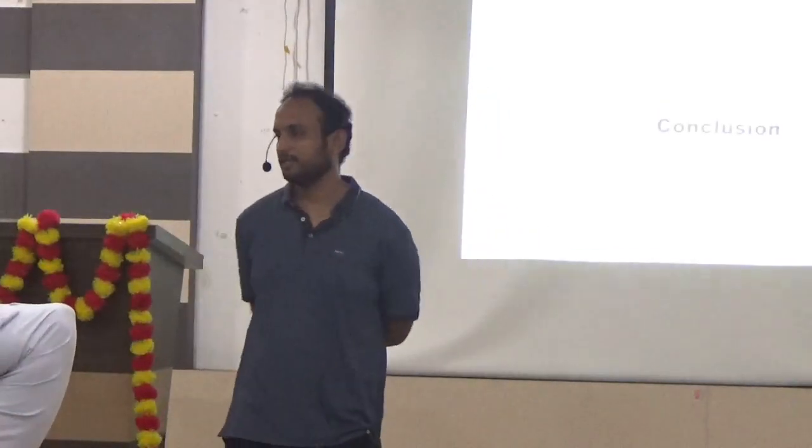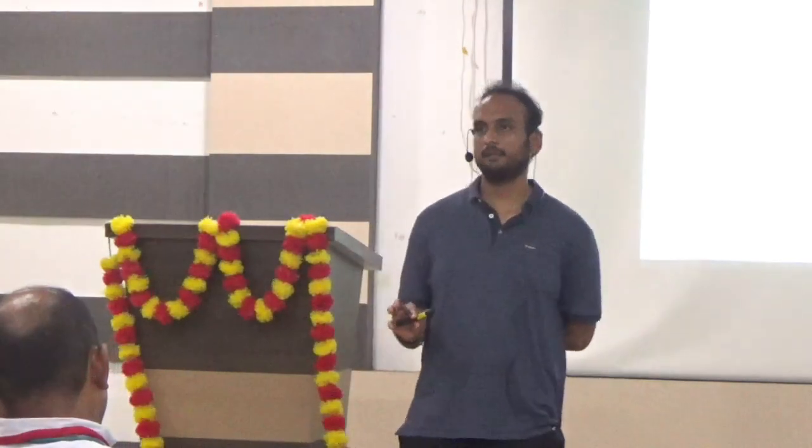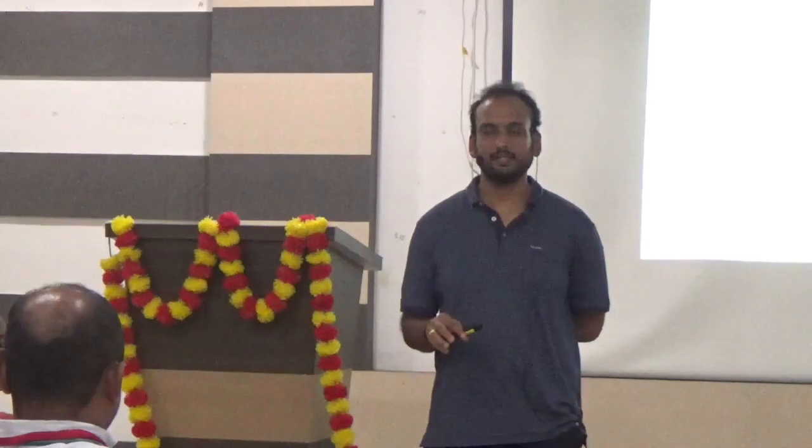Very basic. Speed is okay. Speed I think both are comparable because it depends on fT. So one major important factor, apart from all these differences, is the self gain, the intrinsic gain of the device. In the MOSFET you will not get high gain, but in BJTs you will get higher gain.